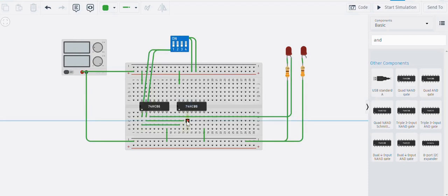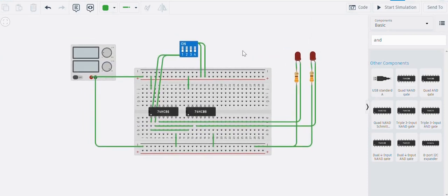So the output we get here is for the carry, and we connect it to the anode. So basically our HalfAdder is ready, and now we can name it here. So we give sum here, and here we can name it as carry. So we can start the simulation. If there is some error, we would resolve it, or else we have made our simulation part correctly. So we can proceed further.